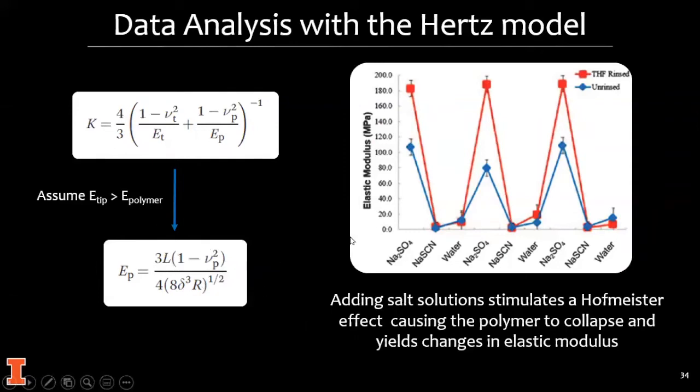Once you do this, you can get an estimate of the reduced modulus, and if you cycle through the different environments, you can get an idea of how your modulus changes. NiPAM is also a temperature responsive polymer, so just to let you know, you can do the same thing with temperature, and MRL has a polymer heater, so we can do these measurements in our facility as well.